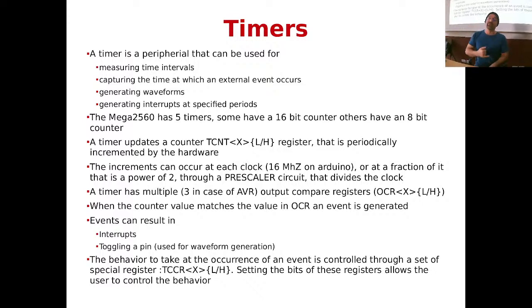In addition, if you have a timer at 16 bits, the library defines also two additional fake registers that do not exist, which are count high and count low, that map to the higher and lower bits of the register. But we don't care about that, right? Because the AVR can read only 8 bits at a time, and so sometimes if you want to use pointers or stuff, you might want to access it 8 bits at a time.